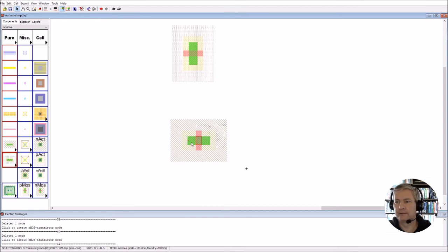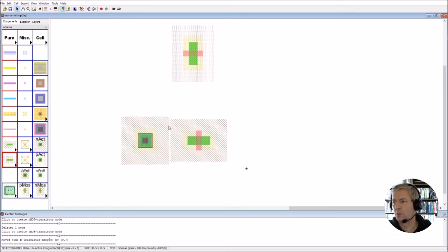So to get access to the active region, we're going to have the contact. So there's the N active. So it's an NMOS device, so we need to get an N active connection. So you can see here that the well is a P well, and it runs in this direction, all the little lines. So we'll just leave that there for the moment, and then we can grab another one of these and we'll put it to the other side.